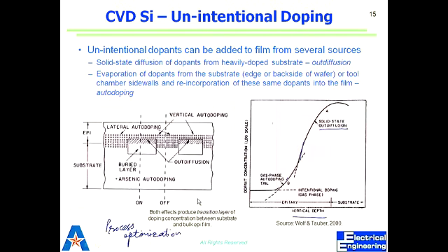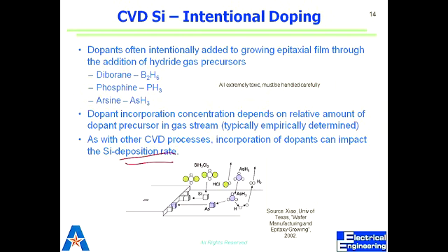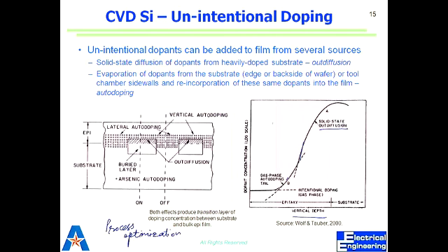So then we don't have to do the implantation afterwards. But once we do that, it can happen that at high temperature we get two processes, which is autodoping and out diffusion. Out diffusion is they would start growing in the other directions, and autodoping they would go out and then dope at other places where they are not supposed to go.